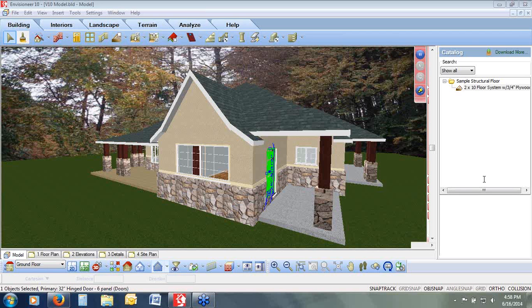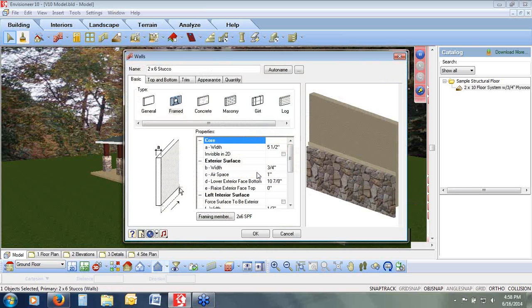Can I select structurally insulated panels as part of this program? When you're doing the walls and you're creating the designation of the wall itself, you could set it up, and the default catalog, you'll notice, has ICF panels in there. It's how you designate the wall and set that up. So if you wanted it to be set up as a panel, you can.